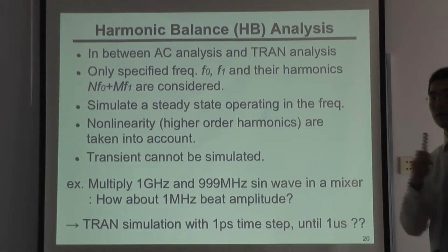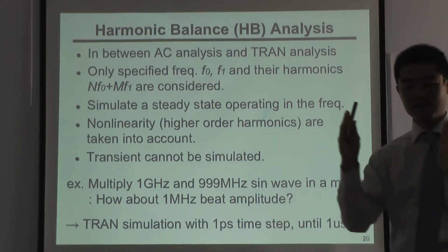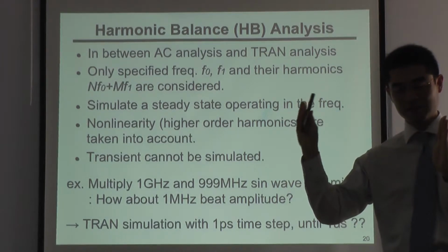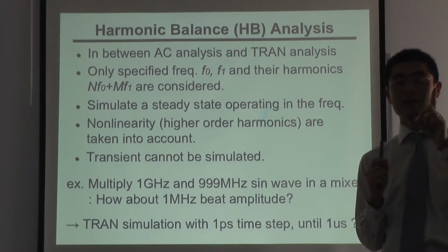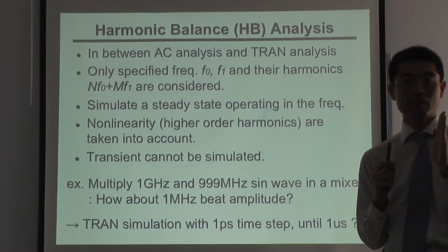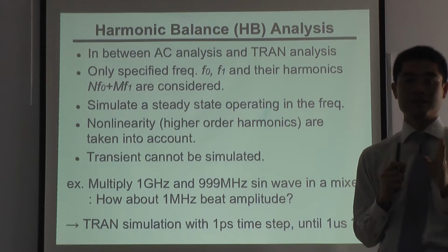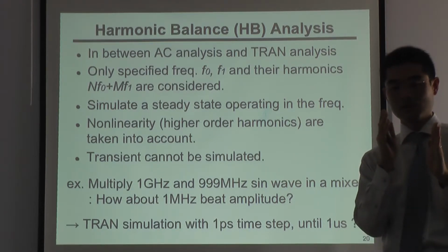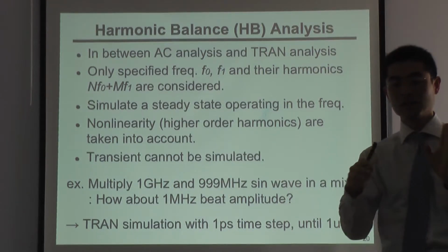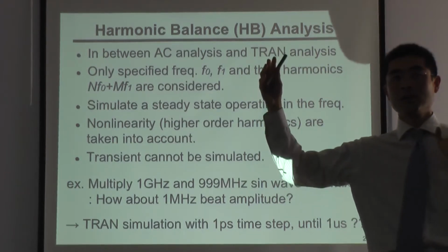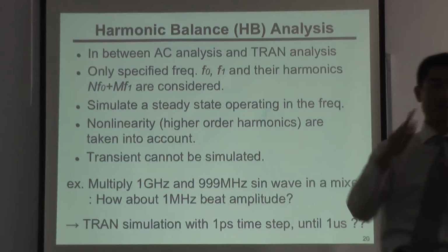Harmonics means it takes the nonlinear effect into consideration. If the harmonics is 1, that means only the main frequency, so 1 harmonic means the same as AC analysis. And once we have, for example, 8 harmonics, we can consider more nonlinear effect, and if we have 100 harmonics, it completely traces the nonlinear effect.